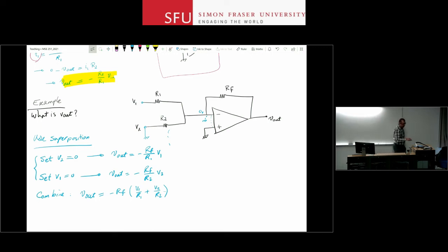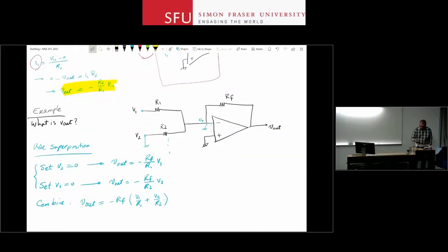So that's really not an interesting answer. But if you go back and think about what we said for the inverting amplifier, what you're doing here is converting V1 into a current, converting V2 into a current, converting V3, V4, all those signals into a current. And if you want to add currents, it's super easy. You can add currents at a node. So what you do is convert all those signals into currents, bring them to this node, and add them up. Now the input resistance that is infinite for the op-amp, or the current that is 0 for the op-amp, lets you reroute that current, created from the addition of all those, through RF and produce a voltage signal